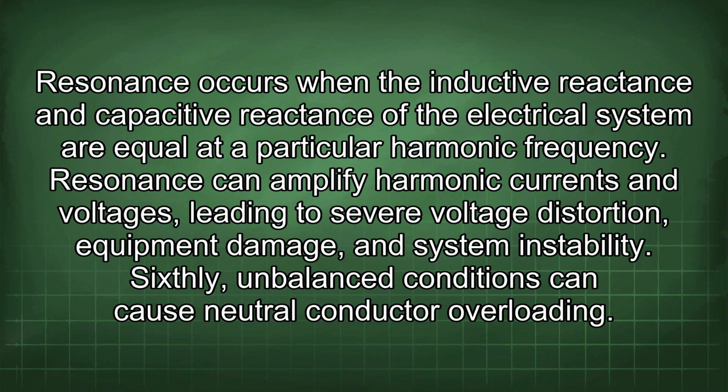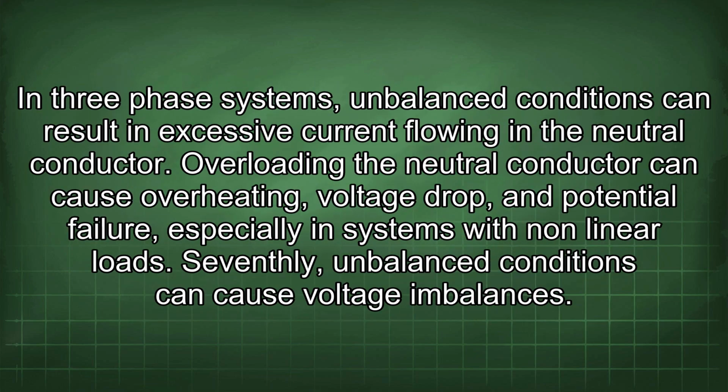Sixthly, unbalanced conditions can cause neutral conductor overloading. In three-phase systems, unbalanced conditions can result in excessive current flowing in the neutral conductor. Overloading the neutral conductor can cause overheating, voltage drop, and potential failure, especially in systems with nonlinear loads.